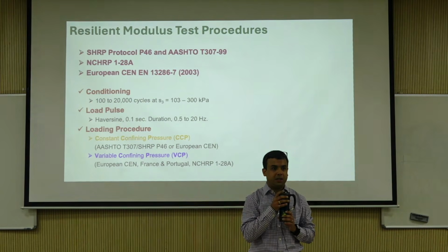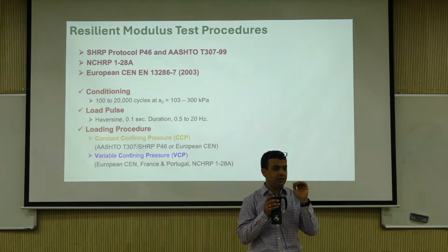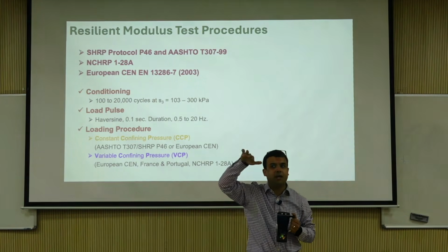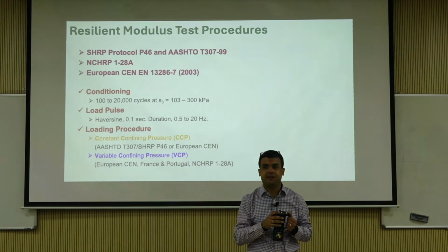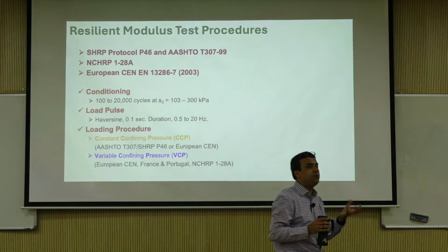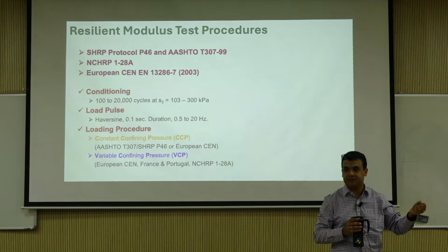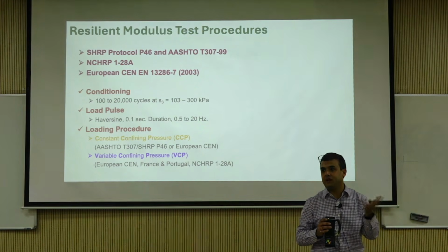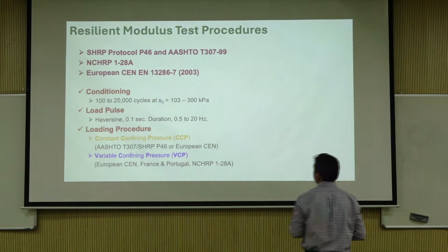Heavier usually, and they are running directly on top of the layer, whereas trucks are running on the asphalt layer or the concrete layer, which dissipates the stress. In conditioning, you should definitely be applying greater magnitudes of stress, because compaction and initial reorientation happen under greater stress levels.